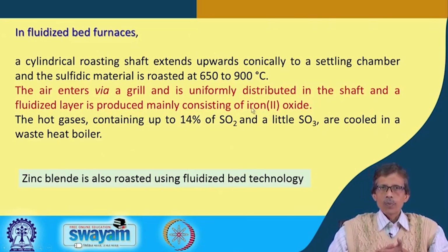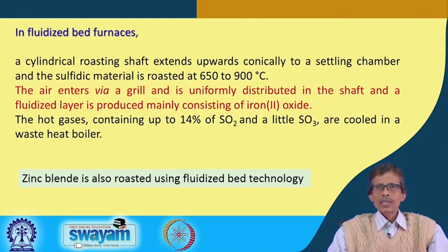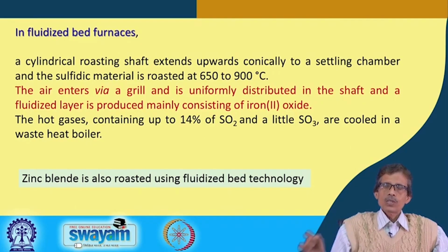So, during that oxidation process, all the particles of FeS2 will be oxidized and we get that thing. That means we are only interested in getting that particular material as a gas. So, if your solid material remains intact and is only converting from FeS2 to Fe2O3, we are happy to have the corresponding oxygen for the burning process as sulfur dioxide. So, air or O2 is entering the chamber and SO2 is going out from that chamber, converting your FeS2 to Fe2O3.